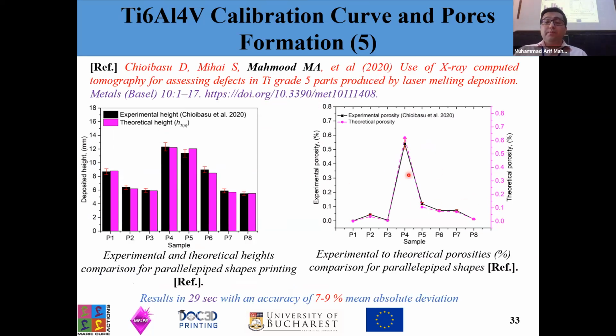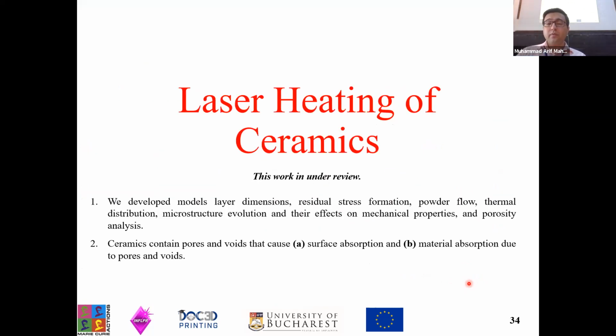So to validate our model, we used some results from one of our previous studies in which we deposited parallelepipeds using the LMD process, and we analyzed the parallelepipeds with the help of XCT. And we can see a very close correlation between the experimental and the simulation results with a deviation of 7 to 9%, and the results were achieved within 29 seconds. So up to now, we did some modeling and experiments for the layer dimensions, residual stress formation, powder flow, thermal distribution, microstructure evolution, mechanical properties, and the porosity.